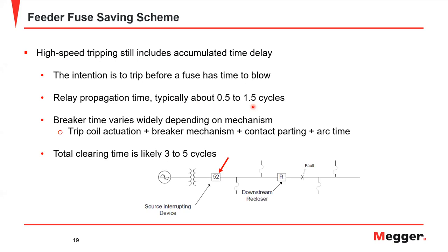The newer relays hitting the market now are getting a little bit faster than this. They use static outputs and they can switch on. I've actually seen one down now to 0.2 cycles. I don't know how common that's becoming, but it is something that's breaking into the market.